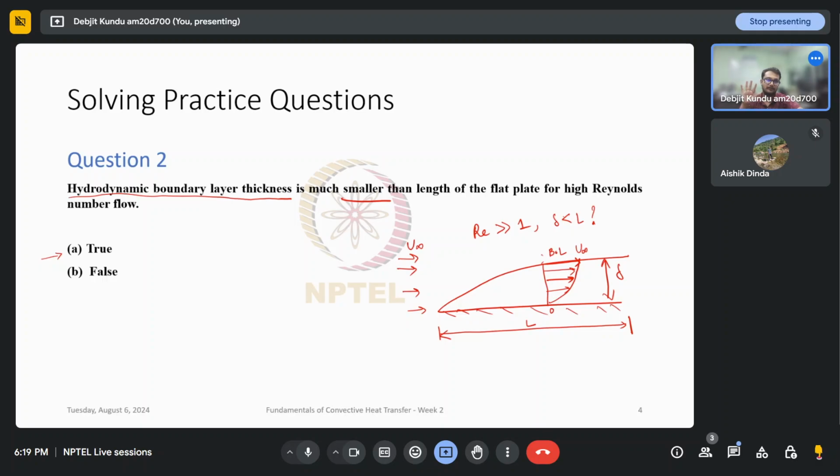In case of fluid flow, the boundary layer dictates the drag and lift on the aerofoil. In case of convection, we will see that the temperature gradients within the thermal boundary layer will dictate the rate of convection out of that solid boundary. So these are important nonetheless, in spite of being very thin.